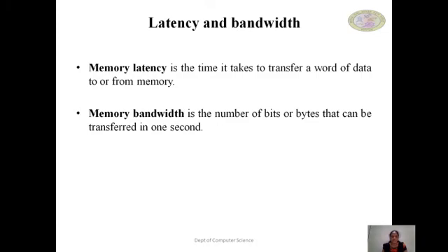In the timing diagram, as I told, first we need to activate the row. The row address will be latched using the RAS signal. So the access cycle begins with the assertion of a RAS signal. Then the first word of data is transferred after 5 clock cycles. So we can see that the latency is 5 clock cycles. The remaining 3 words are transferred in the next 3 consecutive clock cycles. The synchronous DRAM performs all its actions on the rising edge of a clock cycle.